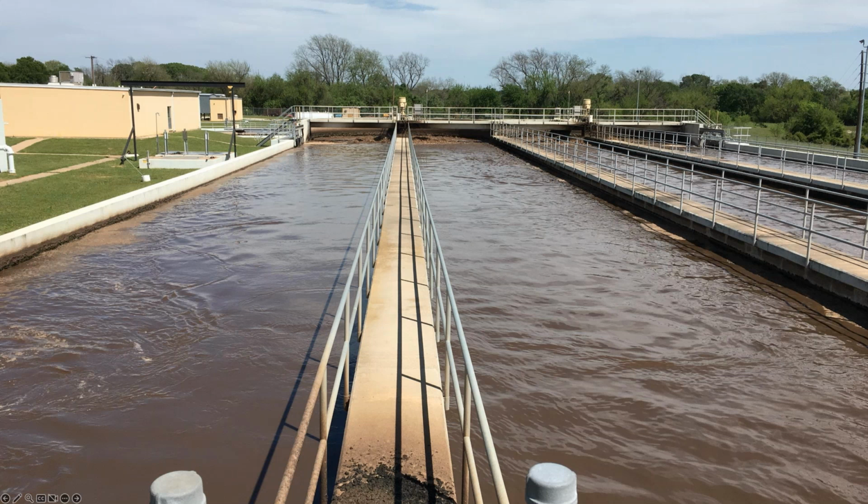Biological processes also need time. You're converting ammonia and nitrates in tanks. Biological processes aren't instantaneous. So having the correct flow rates and detention times is critical. I don't have a diagram of what's going on in here. We'll discuss that in a later session.